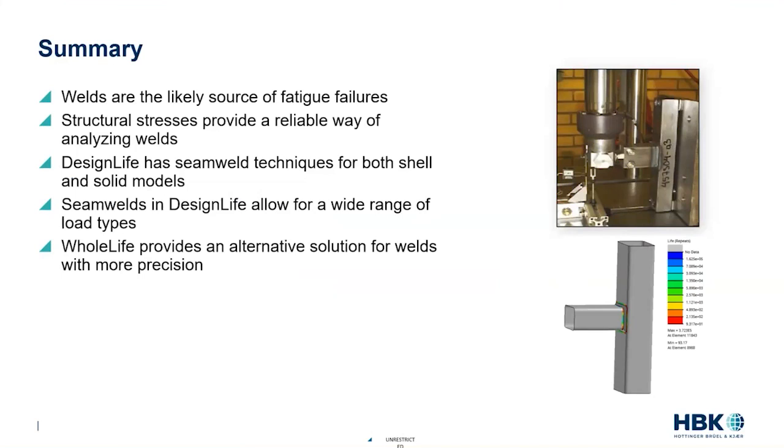We have approaches inside DesignLife for this, both in shells and solids. The Seamweld approaches inside DesignLife basically allow us to use any of the load providers that we have in DesignLife, both time-based and frequency-based. And in addition, WholeLife provides me a way that I can take Seamwelds as a starting point and then add more refinement to the solution to get a better prediction. So if I know more about my weld, I can leverage that to get a more precise prediction on life.